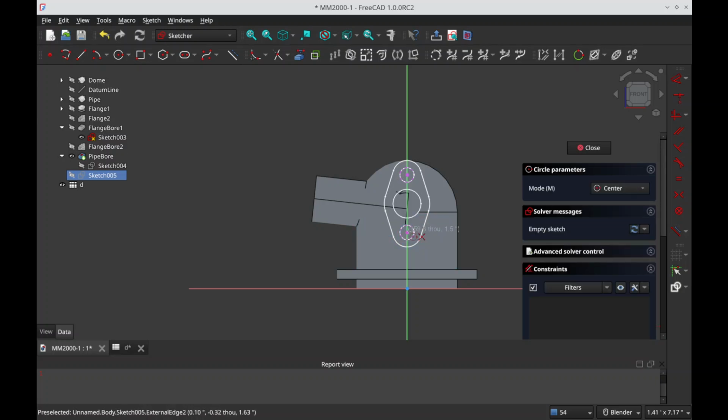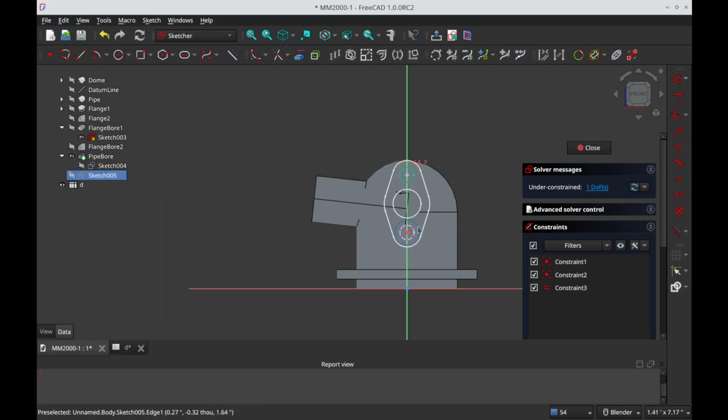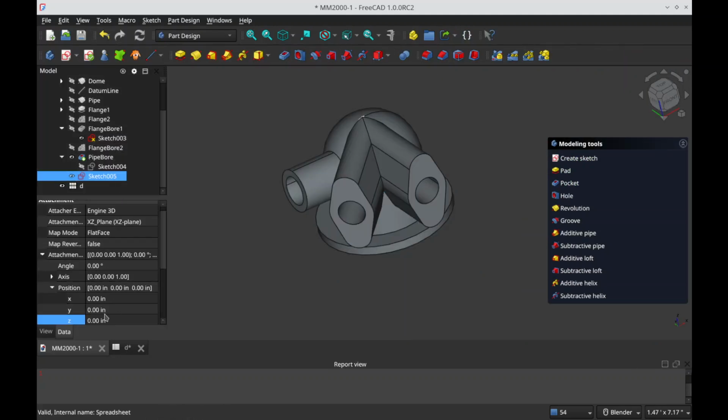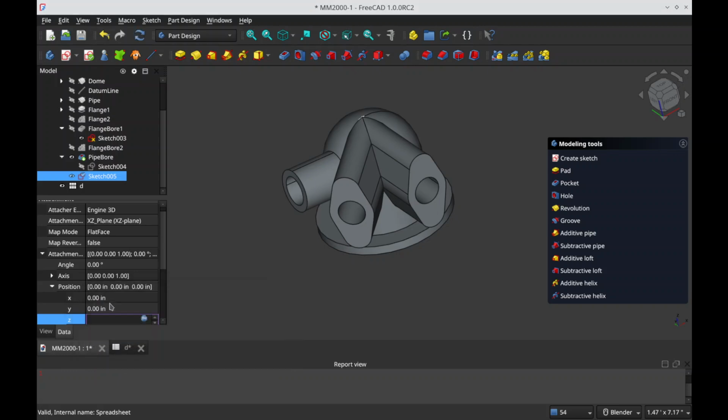And of course, GC to do a circle. I never do the tangent constraint. It just has bitten me in the past where the constraint can flip or some such, and I don't use it. So instead I just click both of them and set them equal. 1, 2, equal. Change this z-axis of the sketch attachment to be the flange length. Now they're on the outside there.